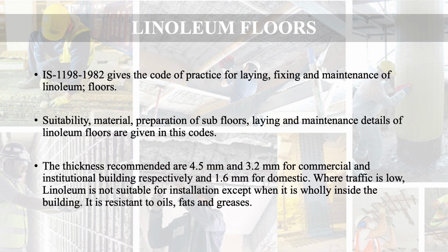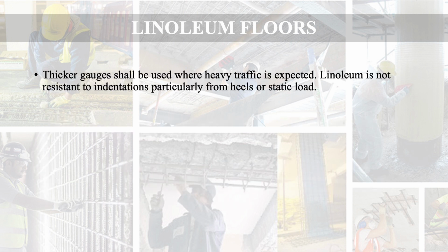The thicknesses recommended are 4.5 mm and 3.2 mm for commercial and institutional buildings respectively, and 1.6 mm for domestic. Where traffic is low, linoleum is not suitable for installation except when it is wholly inside the building. It is resistant to oils, fats, greases. Thicker gauges shall be used where heavy traffic is expected.